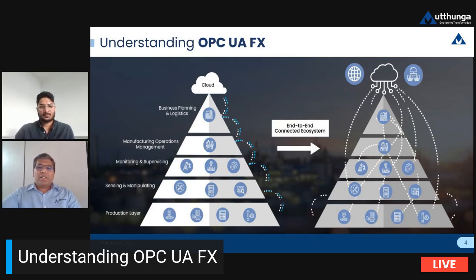So with all this, you would be able to build a system which is interoperable to a very high degree. In addition to this, the technology itself is very much scalable, meaning you can have OPC UA on a very small embedded device with few nodes pushing the data to a very high performance system handling multiple hundreds of thousands of data points at any given point of time.